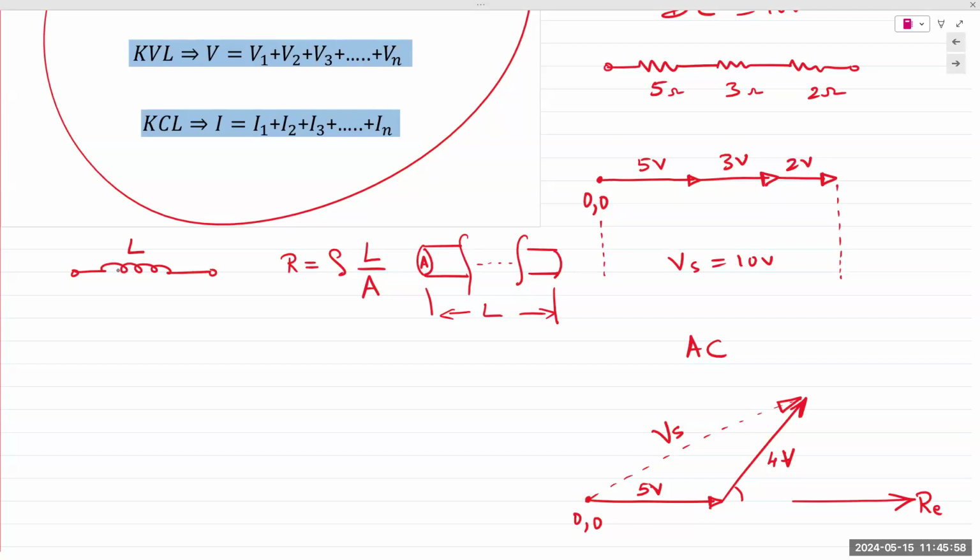So the longer the wire, the higher the resistance. The thinner the wire, the higher the resistance. So if you're making an inductor out of a very thin, long piece of wire, it'll have resistance in real life. Make sense? That resistance is part of that inductor. I just stated, it's a piece of wire.